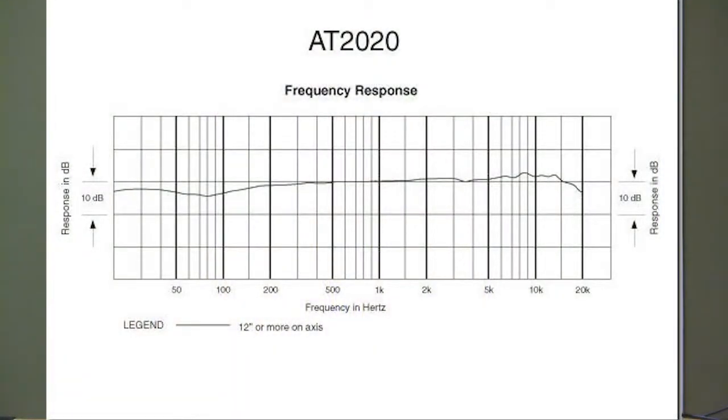Frequency response is the sensitivity to the different frequencies in the whole spectrum. Human hearing goes from 20 Hz to 20 kHz. So microphones tend to try to capture as much of this frequency range as they can, without emphasizing or de-emphasizing some frequencies. This type of response is called a flat response. You can see in this picture that the frequency response of the Audio-Technica AT2020 is pretty flat. It doesn't emphasize or de-emphasize much on frequencies.